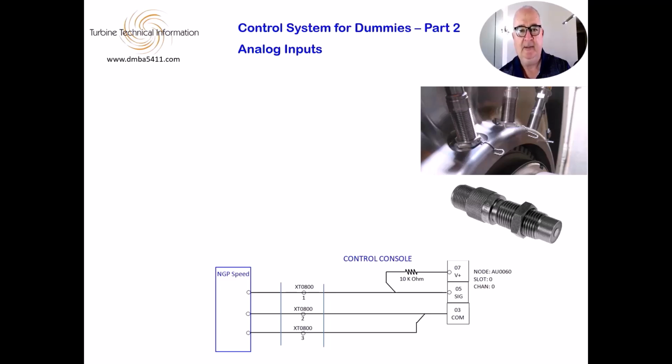To test this circuit, it's straightforward. Although if you have not tested one before, best call on your I&C technician to show you. Set the meter up for frequency reading and take the reading at the Flex IO. Red lead on terminal 3, black lead on terminal 5. The voltage is important, just as the frequency. Typically the voltage will be.